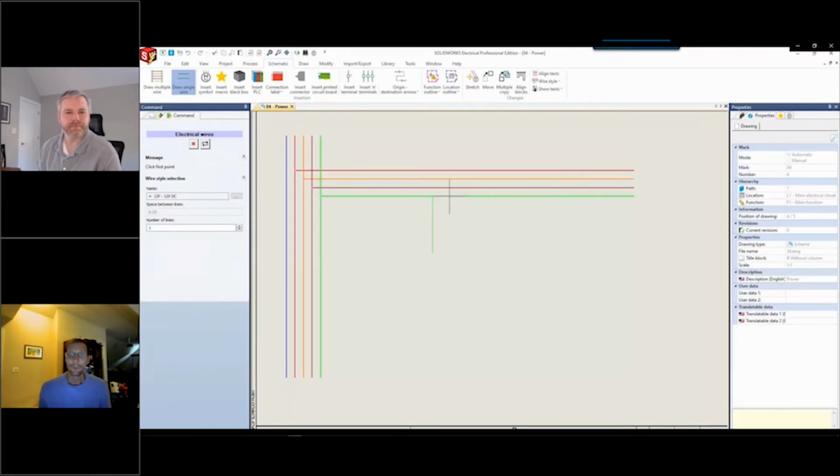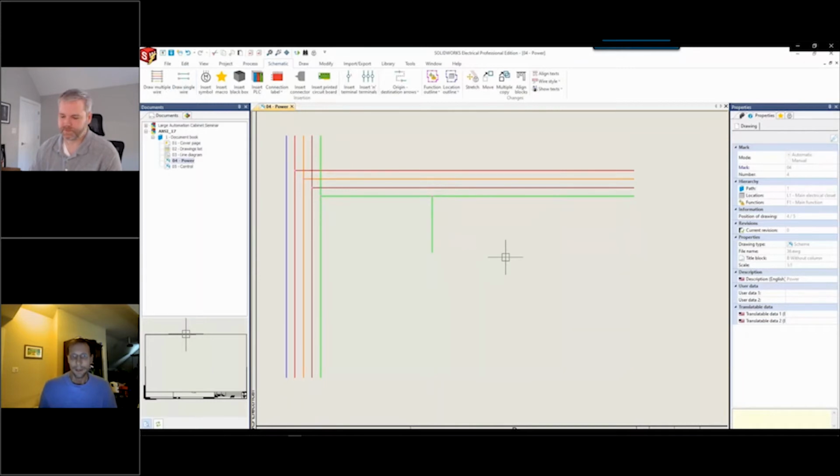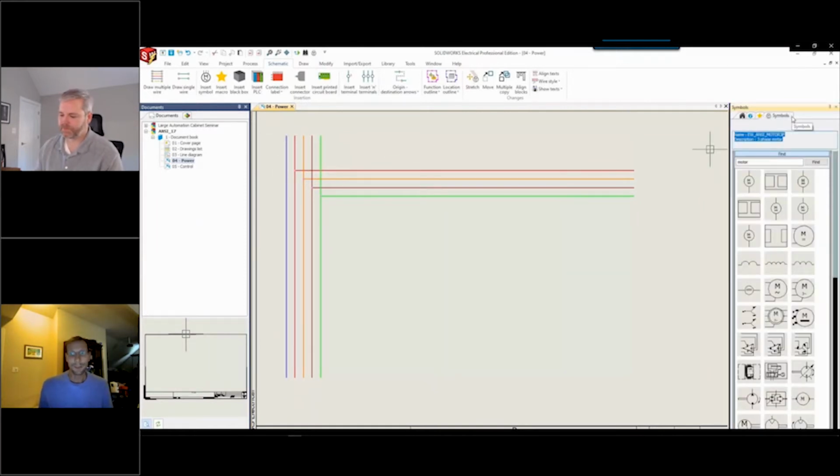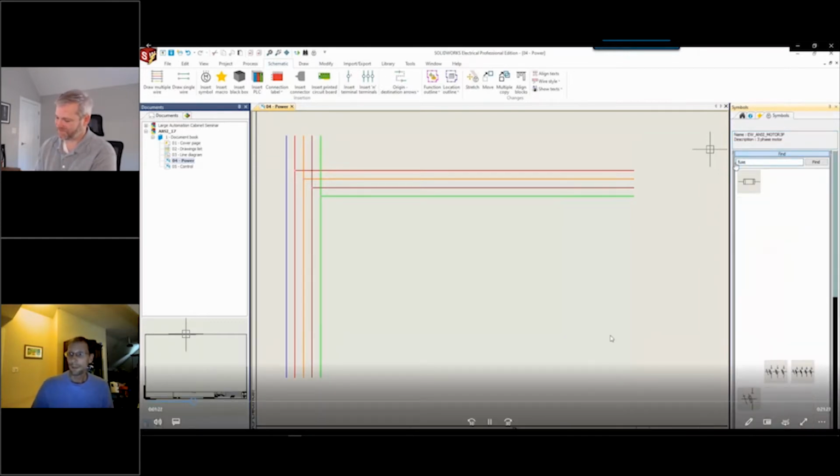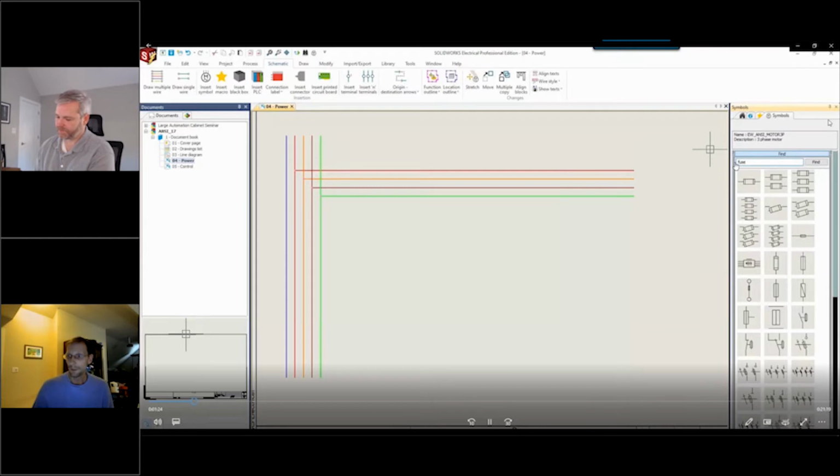At the same time, when I generate a wire that has a connection point between an existing wire, you'll see it generates that connection point automatically and separates that existing wire from continuity. So getting this on the screen, for those of you that have done this in the past, it's real simple. I'm going to start to add in some symbols to this circuit at this point. And we have a couple ways to do it. I can go to my library here on the right.